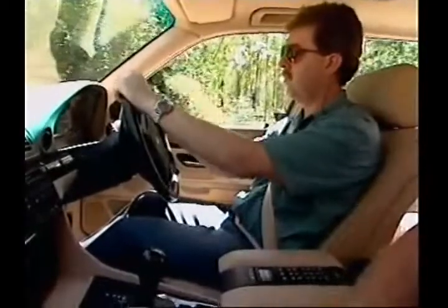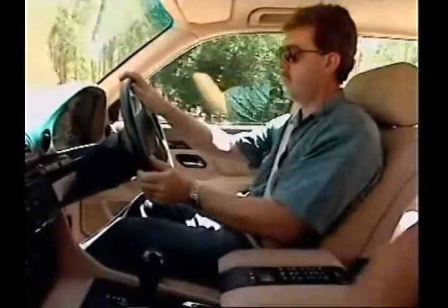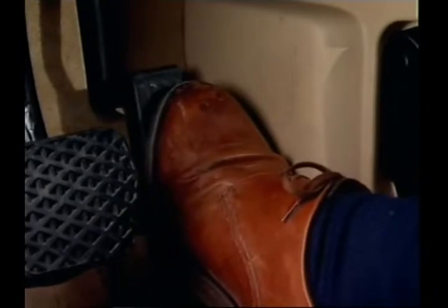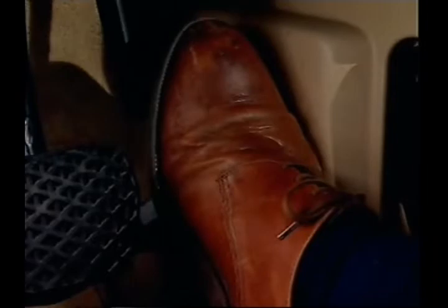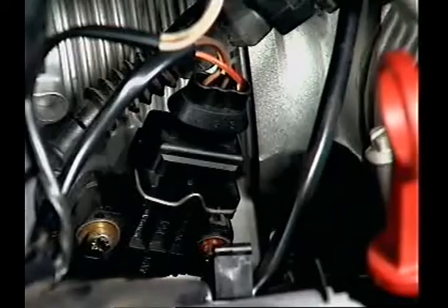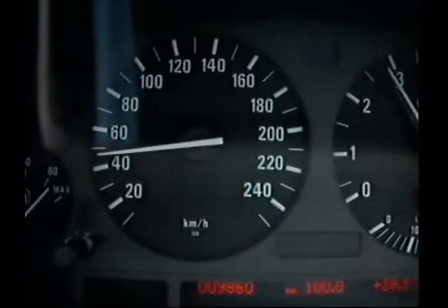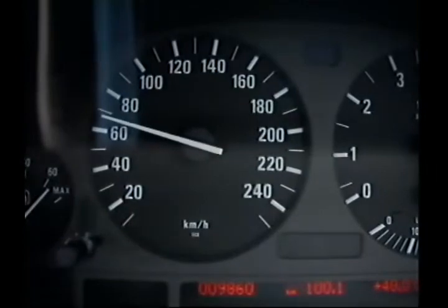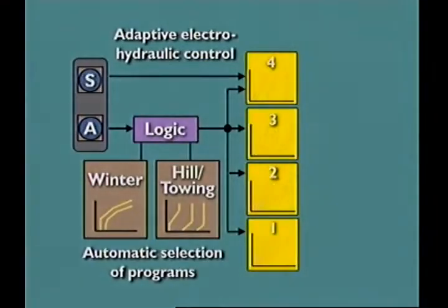Accelerator pedal movement can be evaluated when moving the vehicle away from rest and during regular driving. The length and frequency of kickdown periods can be evaluated, and the speed of accelerator pedal movement, or kick fast. This data from a throttle position sensor, together with vehicle road speed, can identify driving style. One of 4 shift programs can then be initiated.